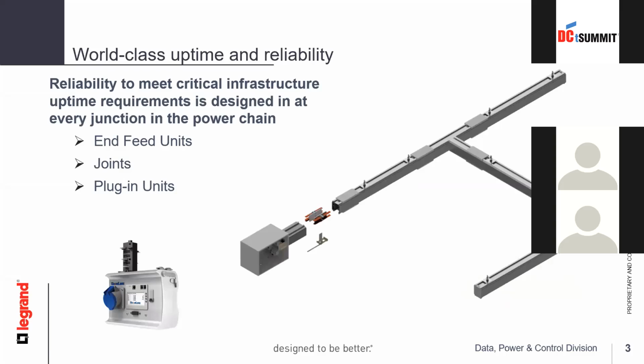Before I go into the reliability aspect, I would like to quickly touch upon the continuous access busbar architecture, just to familiarize the important elements, especially for those who may not be familiar with the continuous access busbar. The entry of the busway is the first point to which the incoming cable from the low voltage panel or the UPS gets connected, and then this entry is connected to the sections of the busway using a joint kit.